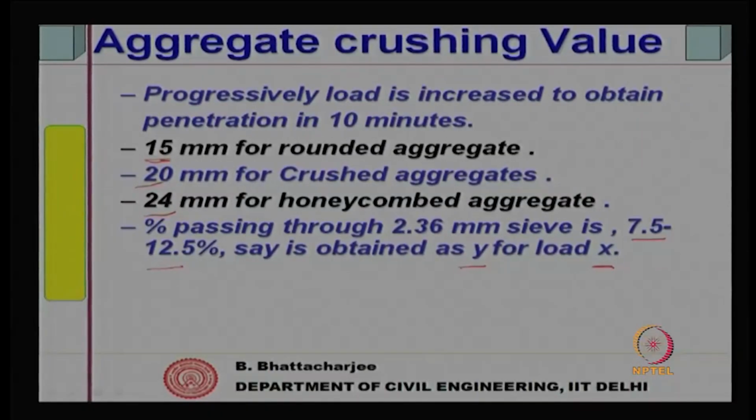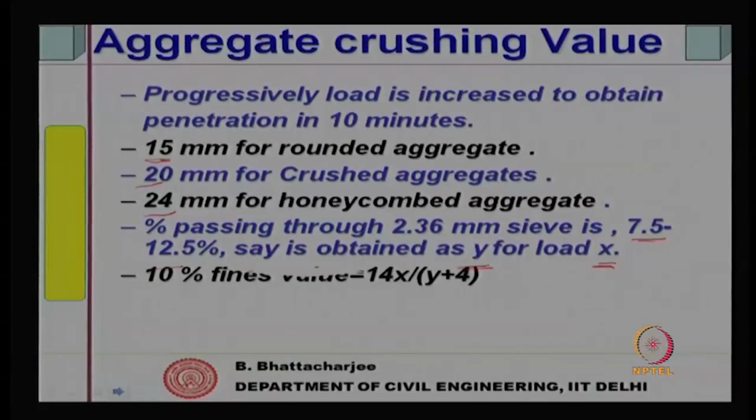And let us say the load is x for y percentage passing through the 2.36 mm sieve. You want to find out the load required for 10% fines.